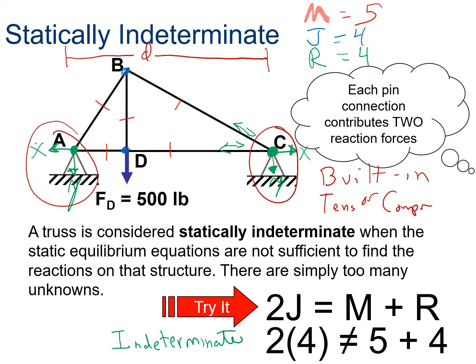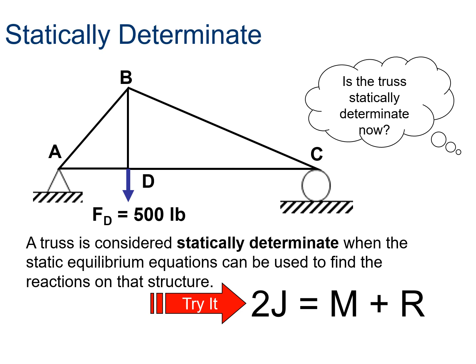And that introduces a lot of variables that unfortunately are hard to quantify, because when you first drive onto this particular truss bridge, you might have some beams that are in torsion, some are in compression, some are in tension, and that's before you even drive anything on there. And so that's somewhat indeterminate when it comes down to it. So our solution will be, instead of a fixed, put a rolling support. And so what that does is,